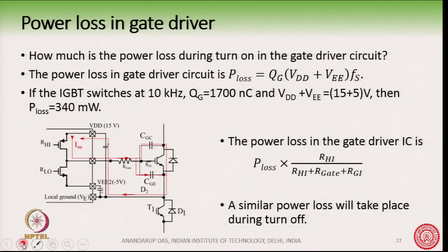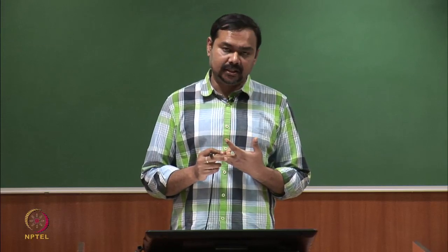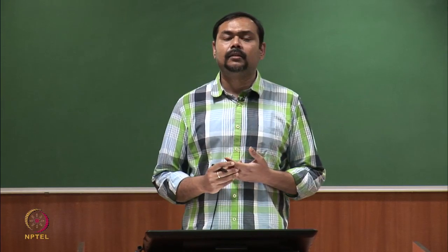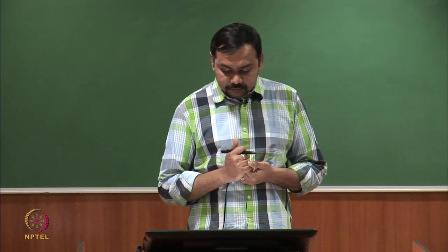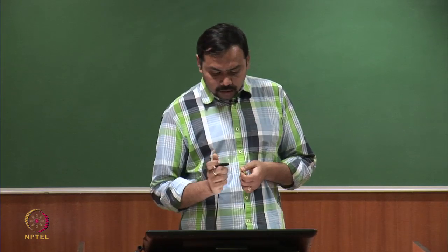Now, what is the power loss in the gate driver as well as in the gate resistance? How much is the power loss? Why is this important? Because when we are taking a gate driver IC, we have to see how much current it can deliver and how much power loss it can sustain to drive this IGBT. So we need to know how much the power loss is going to be.